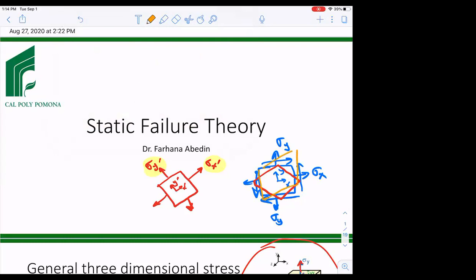If you rotate the planes for different rotations, you're going to end up having different stress values. At one orientation only, you're going to see that there is no shear stress. There's only normal stress. And of all the orientations, for that particular loading case, that orientation has the maximum or minimum normal stress. And we call that the principal stress. Do we understand this now?